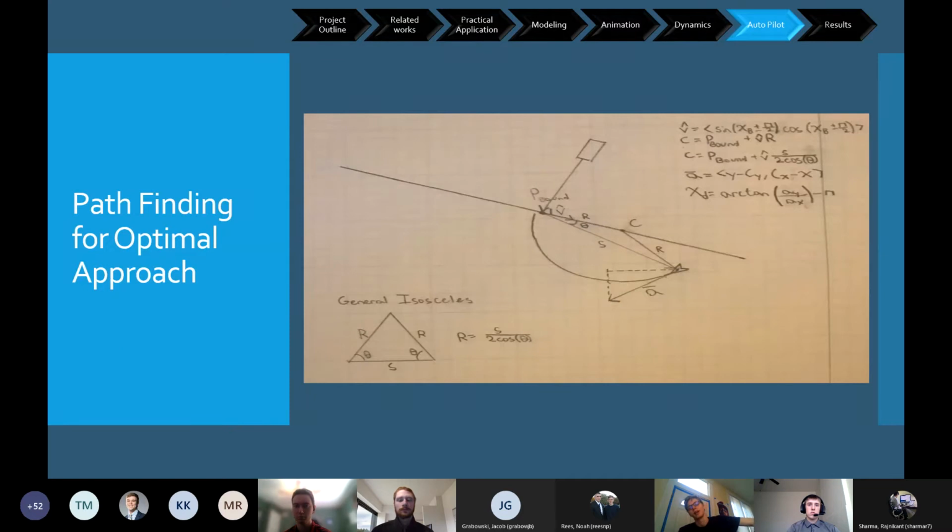So like if we're going the opposite direction, we need to flip it 90 degrees clockwise or counterclockwise. And then just to get our desired course heading, we just take the arctangent of the y component of the a vector over the x component of the a vector, and we subtract that by pi in this case. Once you've passed east or west of the point, you could drop the minus pi term, and then that'll get us exactly to p-bound, and then we just fly directly at the plane.